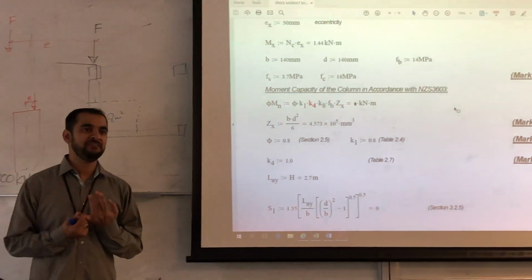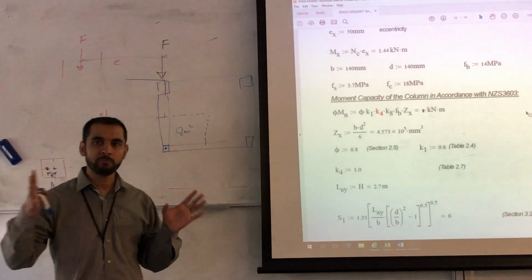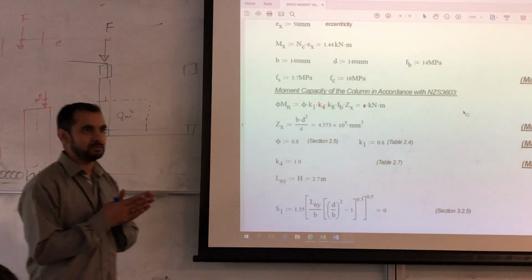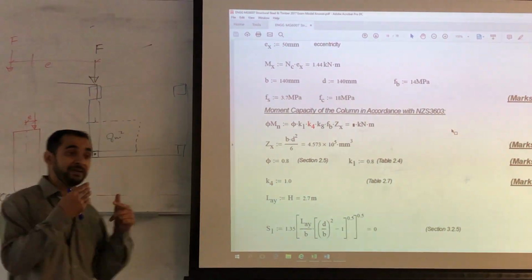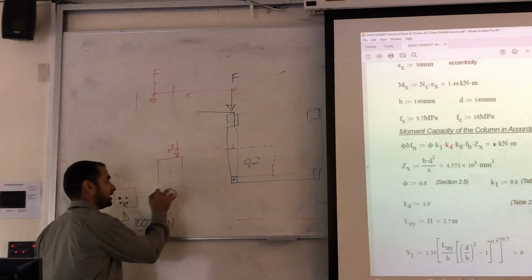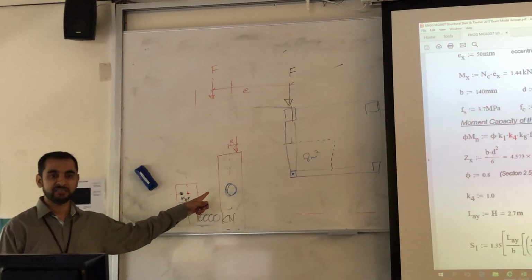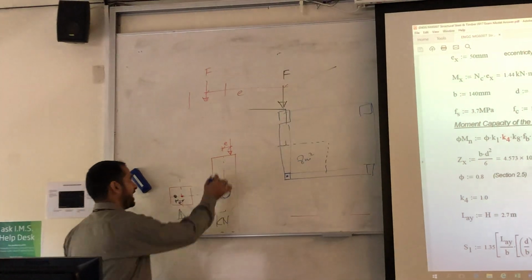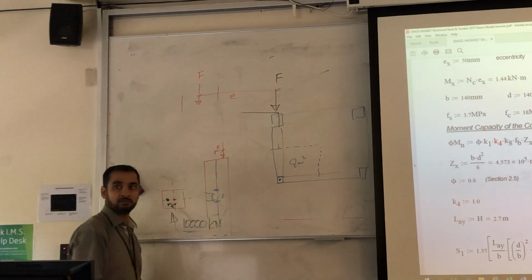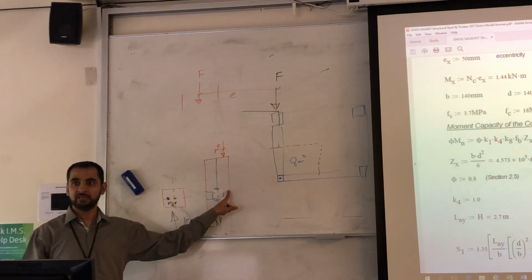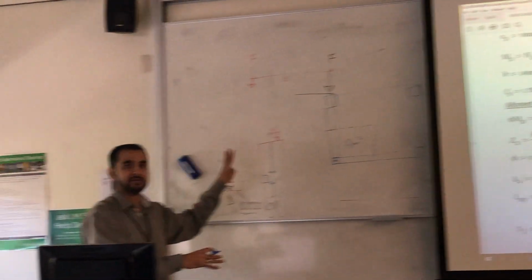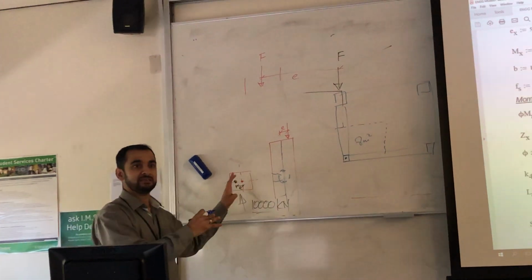Usually in timbers we have defects, right? If it's one member we don't usually increase, but if we have more members, there might be fewer defects, or the defects will not be concentrated at one point. For example, if there's a column and there's a knot here, it's weakening the entire section, isn't it? But if I had two members, and there is a knot, but we got a stronger member next to it. So we got two members, and these defects are staggered over the length. They are not concentrated in one place.